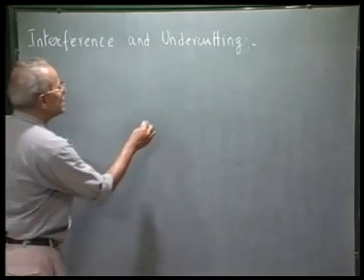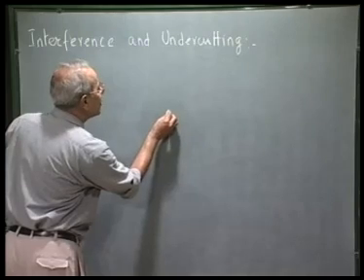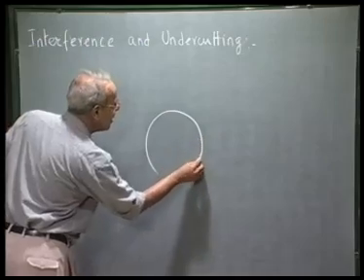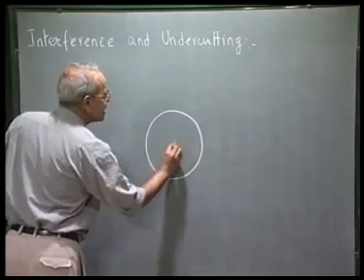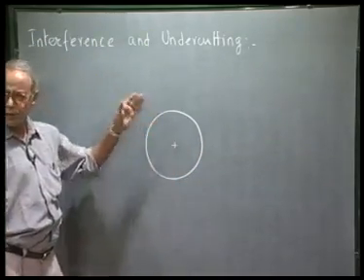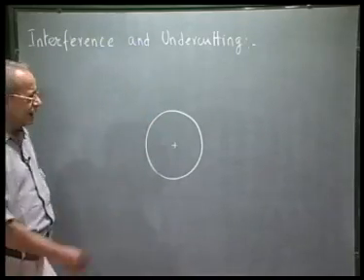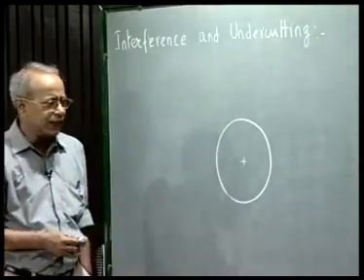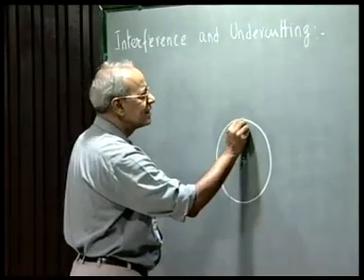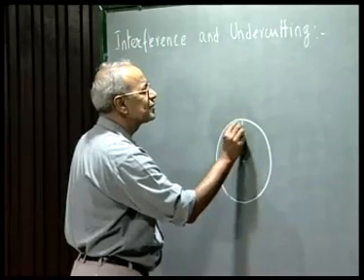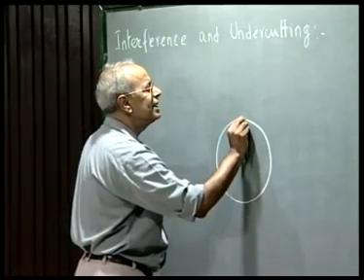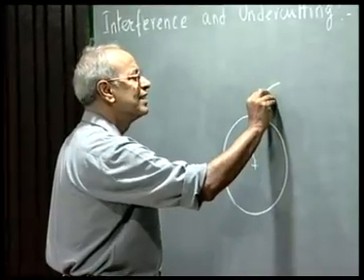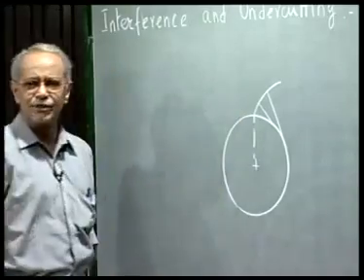If you remember from the very definition of involute profile, it is obvious that the involute does not exist inside the base circle. It is from unwinding from this base circle outward that we created the involute profile. Let us say we start from this point A, it starts radially, and as the string unwinds, we generate this involute profile.